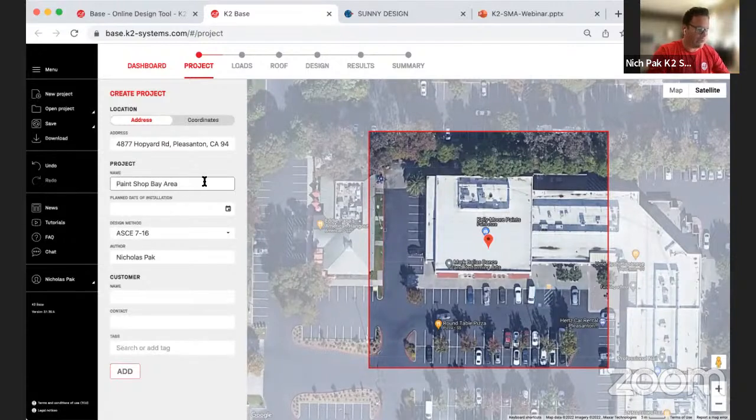And we're going to be doing a very specific product that's great from K2 called our Crossrail tilt system. This is applicable for flat or low pitch roofs. It uses our Crossrail, and it's actually one of the strongest tilt systems that's out there. It's because we take the system and create a rear leg and a perpendicular leg, and then we lay the rails horizontally across it, making it a very robust install. Our goal today is to do 22 degrees on the roof.